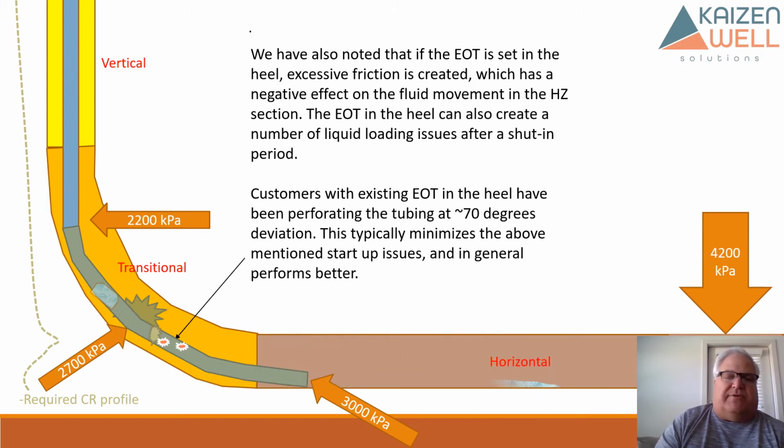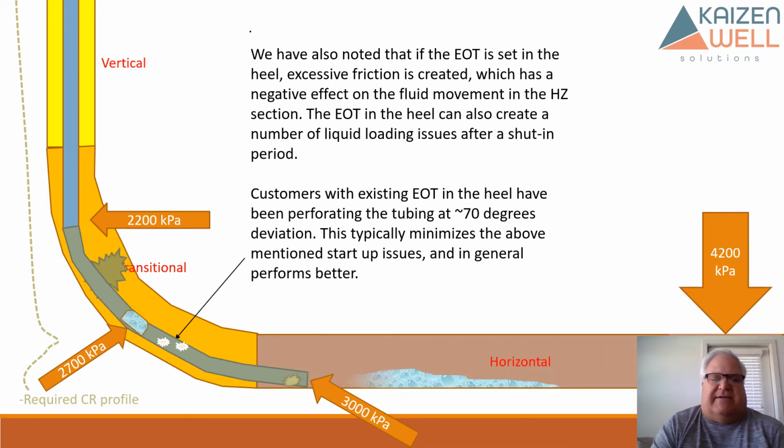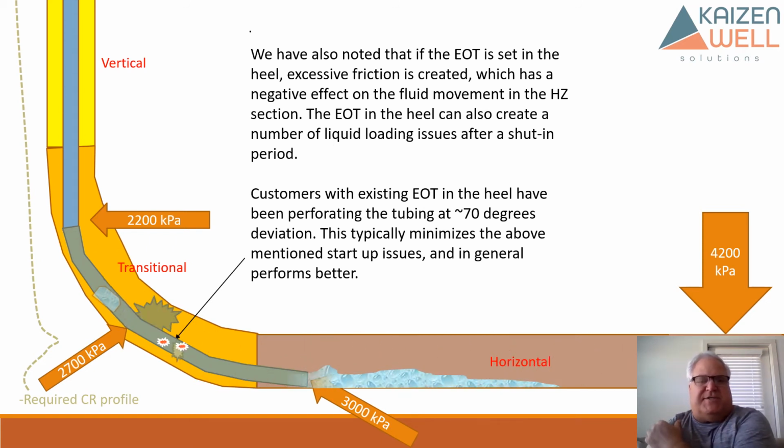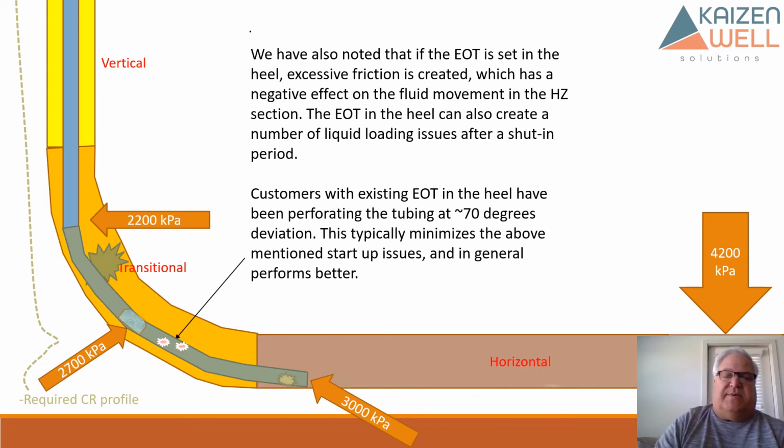Now, originally when we were doing it, we were putting plugs in the end of the tubing and forcing the liquid and the gas to flow around the outside and back through these perforations. And when we talk about a perforation, we're doing like an 8-foot strip gun with 36, 40 shots over that 8 feet to create a really good path. But now we don't bother putting plugs or anything on the end of this tubing. We know that the liquid and the gas is going to take the path of least resistance. We're going to allow gas to enter into this tubing.